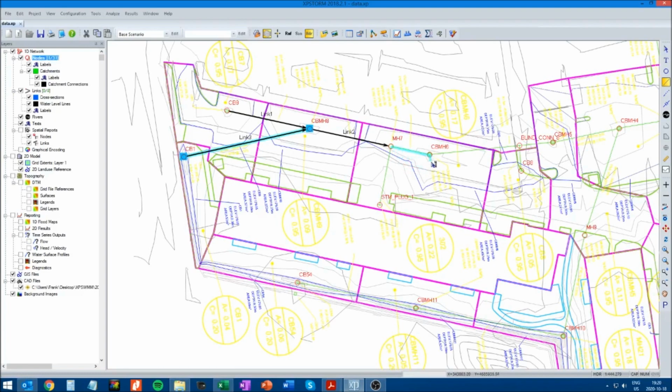Click on the downstream, and hit escape. Upstream, downstream, escape. Upstream, downstream, escape. Or I think you may be able to go 1, 2, next, escape, and it sets it up so you don't have to do each pipe individually.